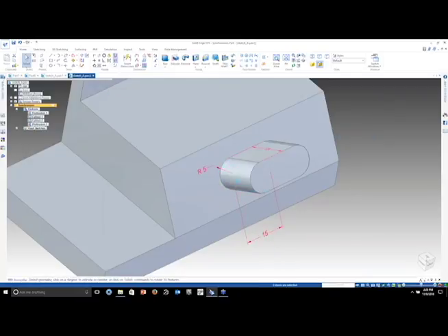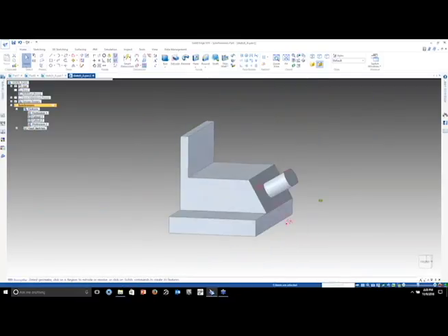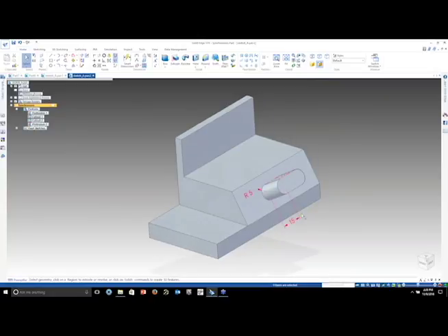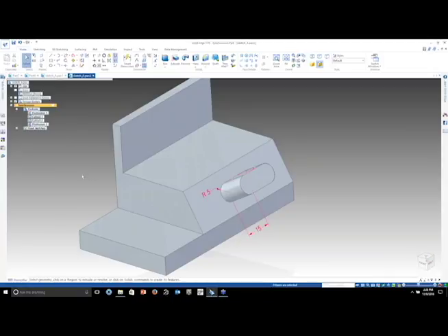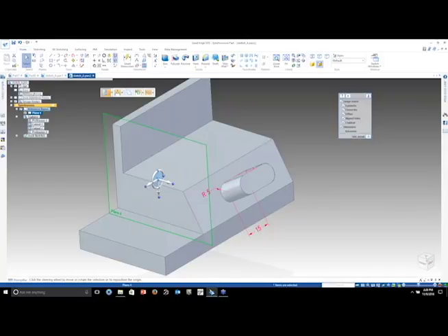Again, once again, dimensions need to be locked because you would want to define how you want this to move. So again, I'd go through and make sure that these are correct. And I want that face on the outside to move. And you only have to do it one time, so at any given time it understands that it wants to move symmetric from there on out. You don't have to pick which direction you want it to move every time. It remembers how that is going to work. All right, so that's drawing on a face.